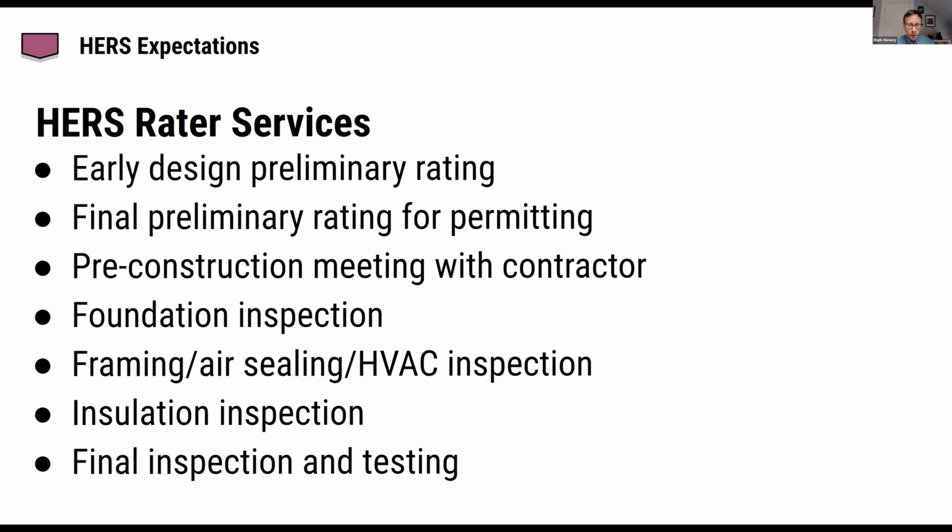And I see a question about what are the goals of the HERS Rater's foundation inspection. Typically, when that step exists, it's to look at any insulation that might be on the outside of the foundation walls or under the foundation slab, as well as a chance to talk about things that are going to happen early in construction that haven't happened yet. So what are some things about the framing of the home that need to be considered now that that's about to start?